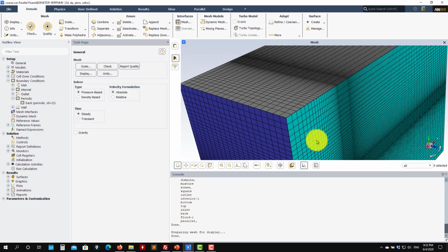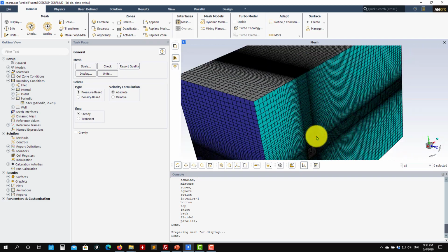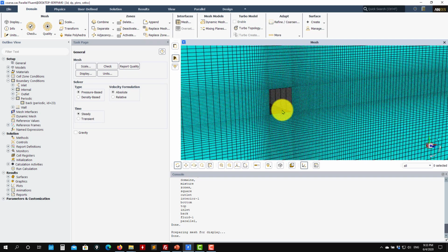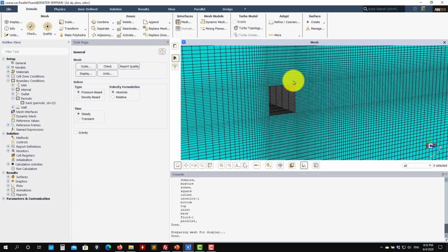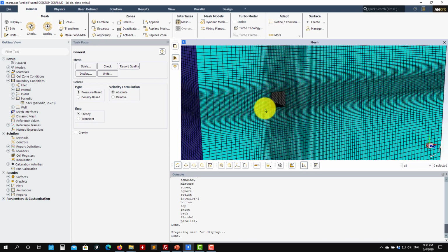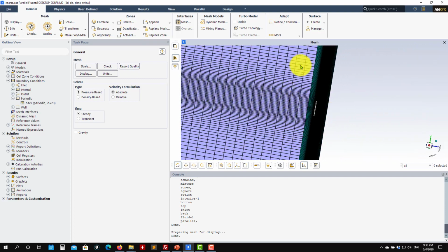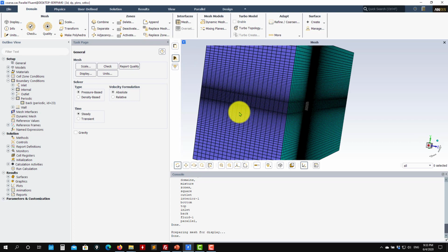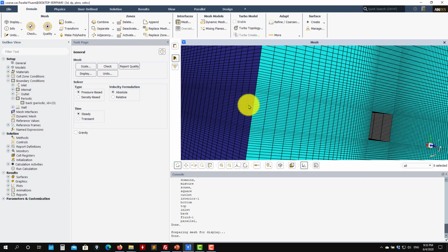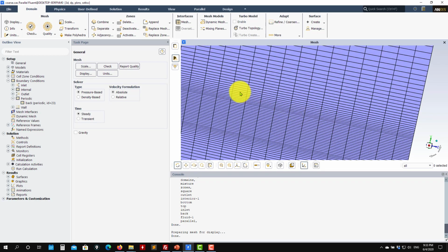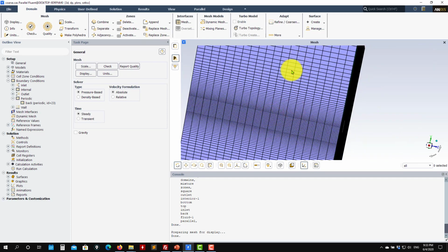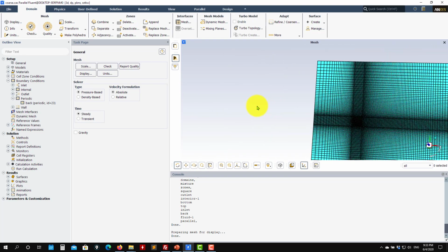So look at that, the mesh is a perfect mesh. So remember when we were addressing the theory, I mentioned that this kind of scale resolving methods, they rely on very good meshes, very good quality meshes. The only thing that you can see here is a little bit of stretching, the cells seem to be a little bit large. We're going to see how to set the quality, but it's true, and this is why we are not resolving the stretch well. In the fine mesh, it is divided by 2, so you can resolve better.